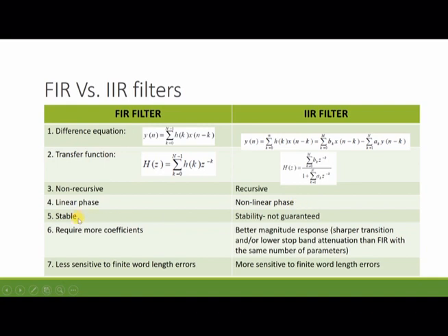FIR filters are termed inherently stable, whereas in case of IIR filters, stability cannot be guaranteed. The reason FIR filter is termed stable is that FIR filters are all-zero filters.